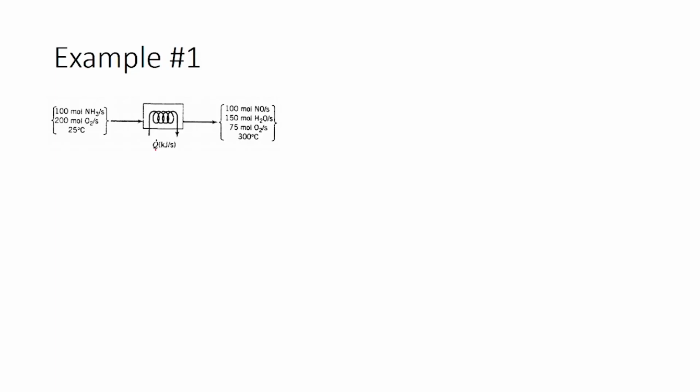Now that we have performed the material balance calculations, we can start with the energy balance component. First thing is the system is an open system. So, the general energy balance equation would be Q dot minus Ws dot equals delta H dot plus delta Ek dot plus delta Ep dot. Ek and Ep do not change, there is no moving part, so shaft work is also 0. So, you are left with Q dot equals delta H dot. This is a simple equation.